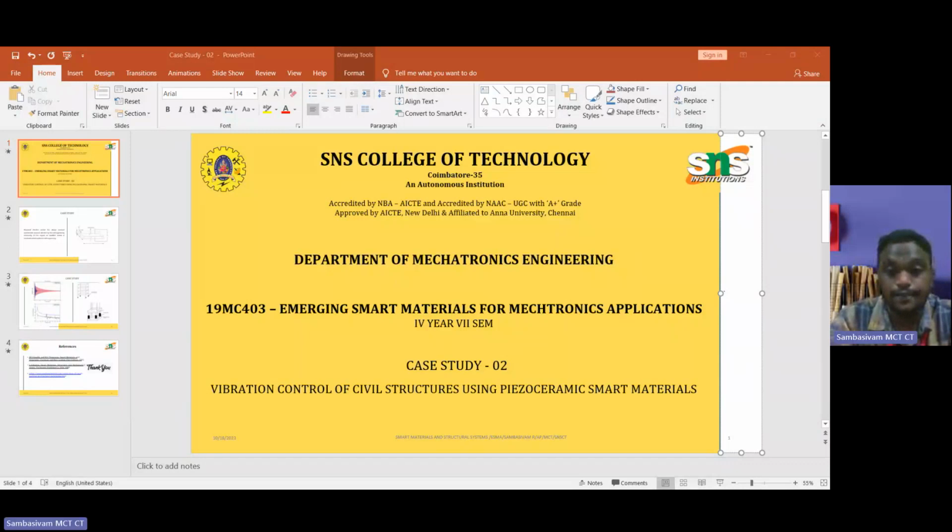Piezoelectricity is found in crystals that have no center of symmetry, such as quartz and Rochelle salt. An important class is ferroelectric piezoceramics, which are ferroelectric materials with perovskite structures such as barium titanate, lead zirconate, and titanate. The ferroelectric ceramic becomes piezoelectric when it is poled. That is the poling direction. This is a modification of solid solutions of lead zirconate and lead titanate.